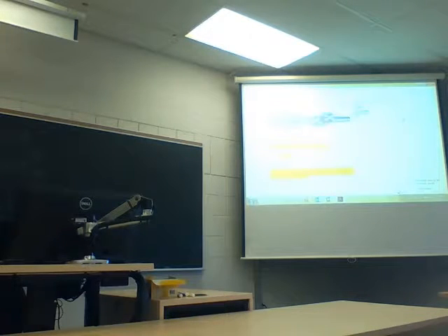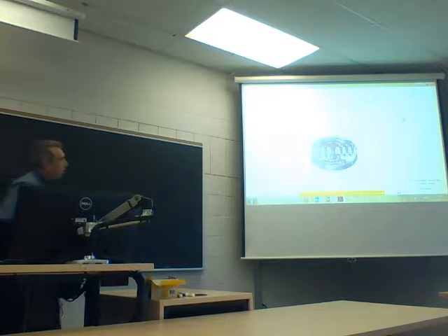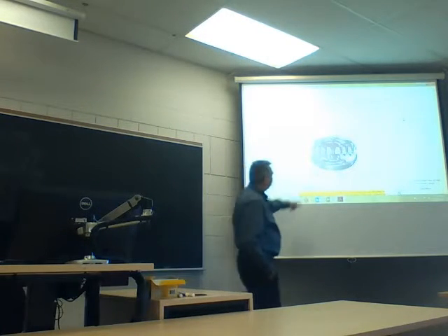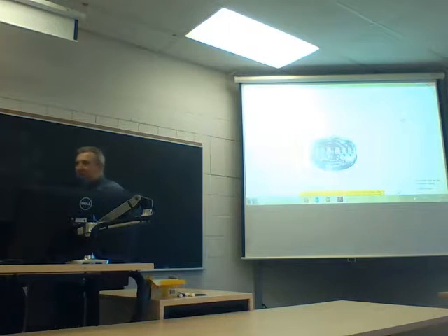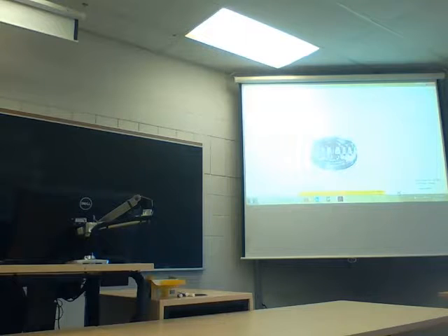Compressor valves. Do they have any questions? Probably a compressor valve, right? Because they are not the normal type of valve. Two different types, the plate type and the channel type. Both operate very similar. Plate type. Just look at the pictures and really read all that, right? Are we good with that? See how these valves work? So you see a little spring underneath them. The spring is just to hold them closed, hold them tight. Not a very heavy spring.